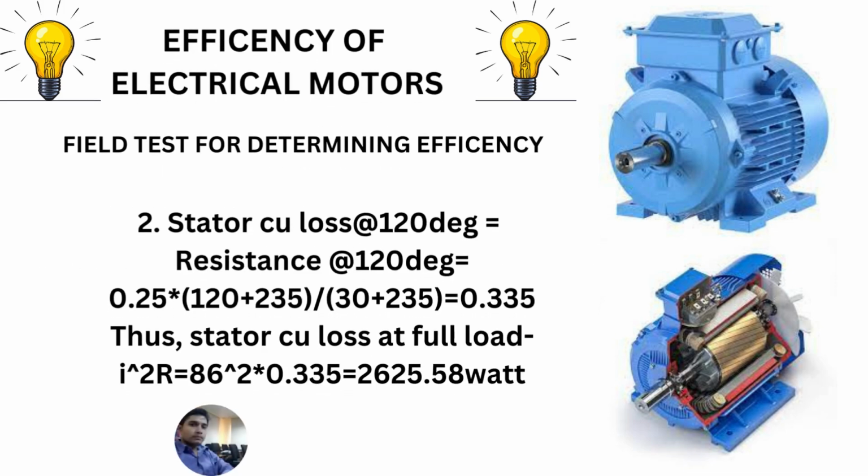Now, step number 2. We will calculate stator loss at 120 degree. Why 120 degree? Because when the motor is running, we are considering the temperature of the motor as 120 degree. It may be less or it may be more, but for example, we are taking it as 120 degree.